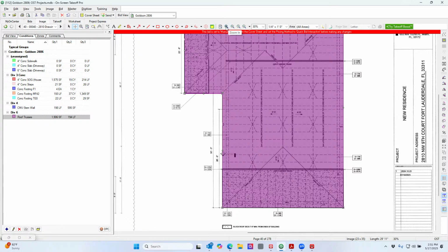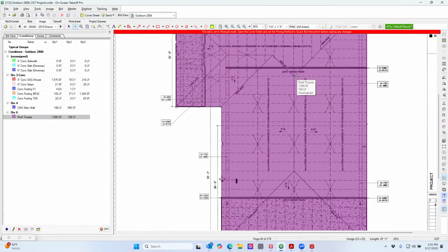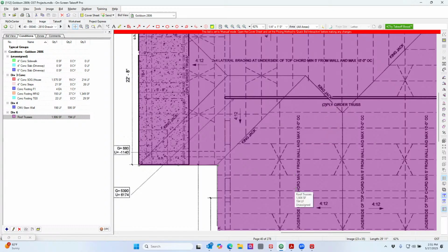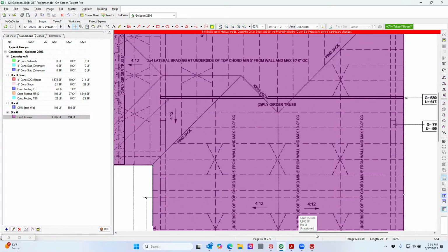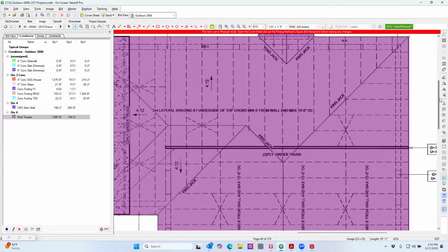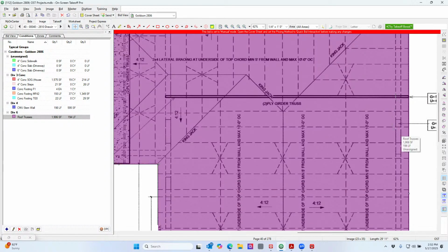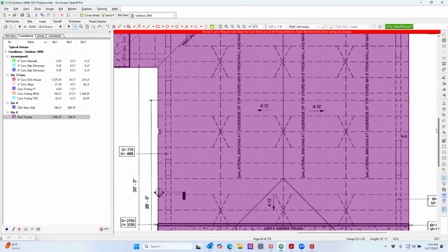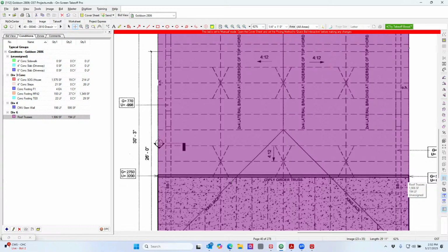It looks like that's the, right, with the footing. It's probably, it looks like some type of girder truss. Yep, that's exactly what it is. So you see where it says 2-ply girder truss? I don't know why that's necessary, but you see how they change the direction of the framing? Most likely, this engineer suspects that because this is changing, you need that support. So a girder truss can hold up more weight. Because that girder truss holds up more weight, it's probably heavier. That's why they made us pour 3 cells over here, which transfers down to the separate footing. So they're transferring that load down to the footing. So that's why those 4 are there.